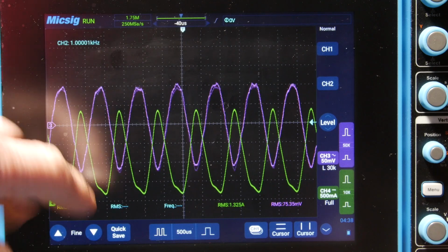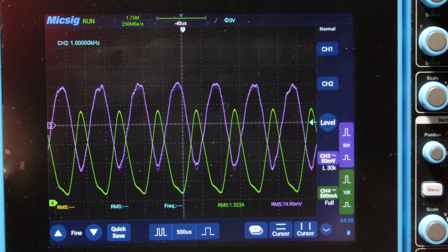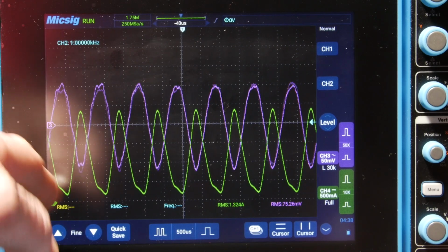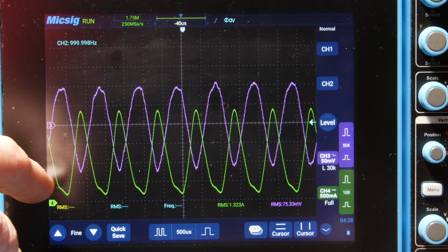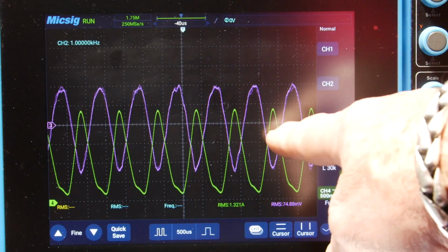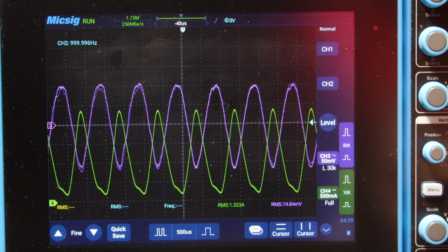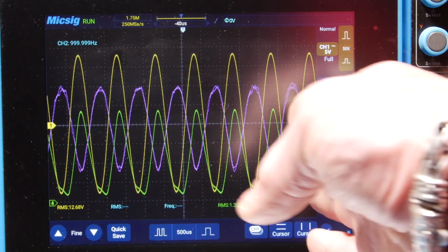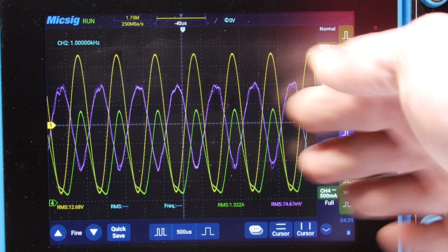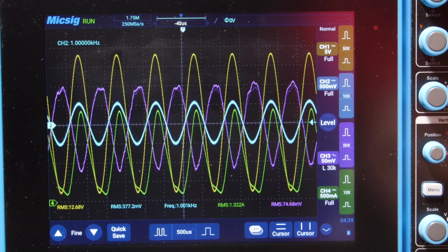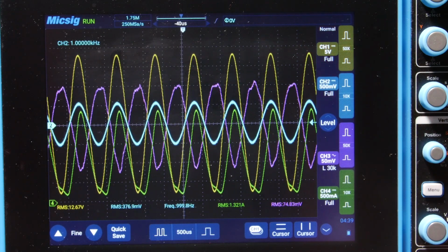There's a little bit of distortion there because it is probably charging caps, running circuitry and all that kind of stuff, but you can see how it is in phase with the output. Let's turn that back on. There we go. It's slightly phase shifted, but it's pretty close. So as the output's drawing current, you're seeing a waveform from the power supply delivering the power.